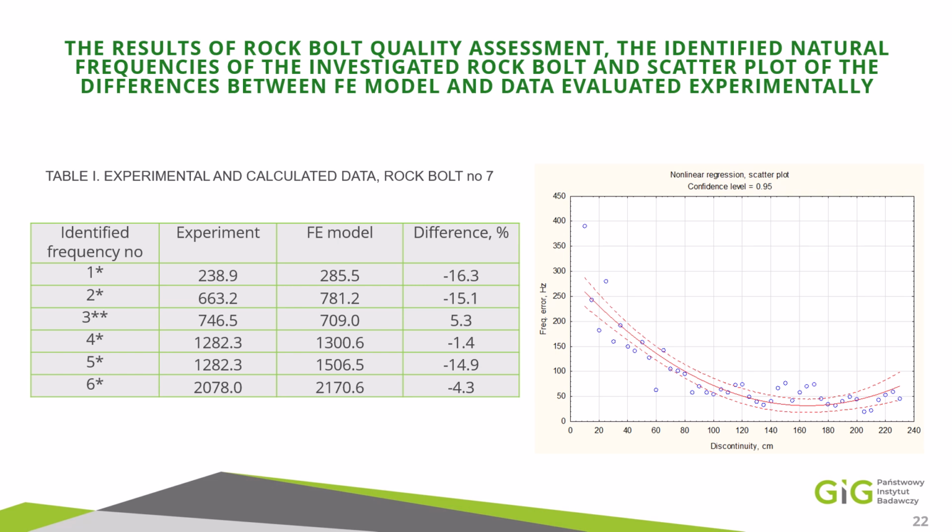Of course, we should also try to find out the reason for such improper grouting, and to start with, we may say that the process of grouting, the installation of rock bolts into strata, consists mainly of 4 technological phases. The first is placement of grout cartridges into a drilled hole using a rock bolt.